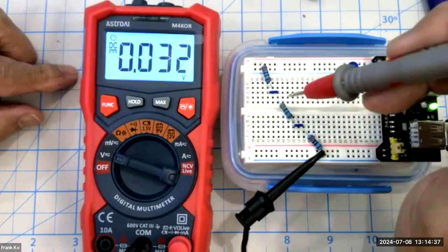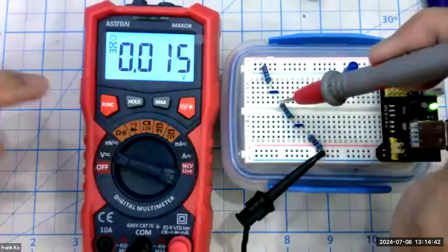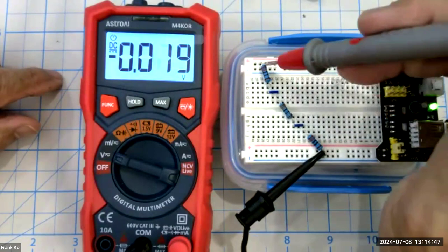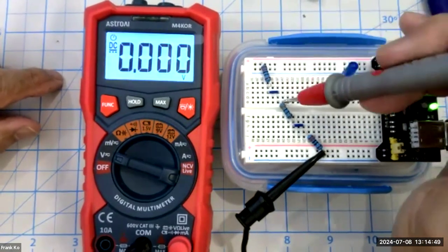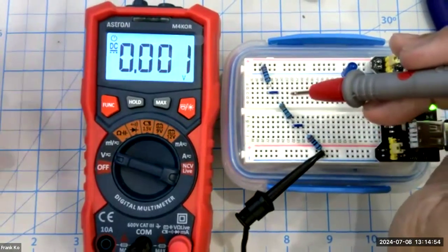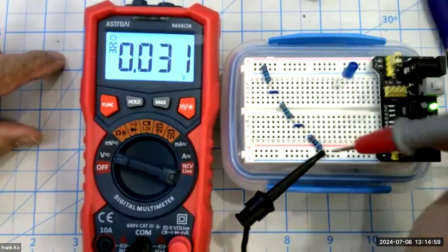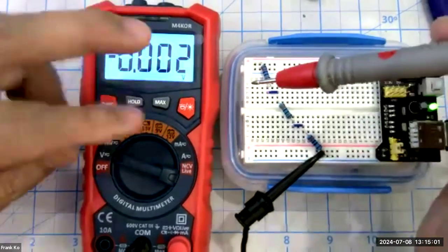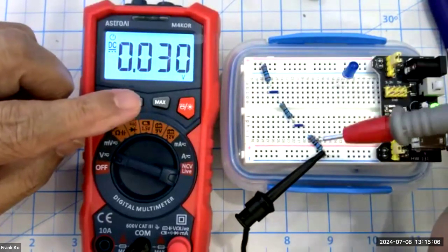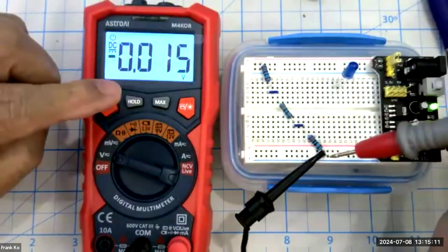If I go to the second test point, which is across the second resistor to ground, it'll be the voltage across 2 resistors. So it should be the sum of the 1.43 plus our calculated 2.14. And if you haven't done that math, it should calculate to be 3.57 volts. Now let's go ahead and make the measurement. Leave that at ground. This is one hand. I've got one hand here to press and hold. The other hand is only holding the red probe.